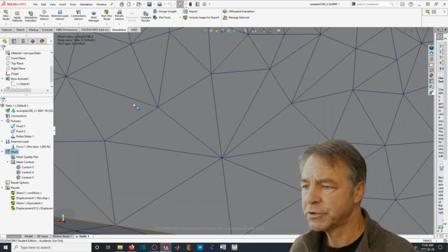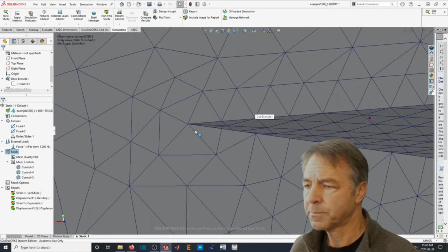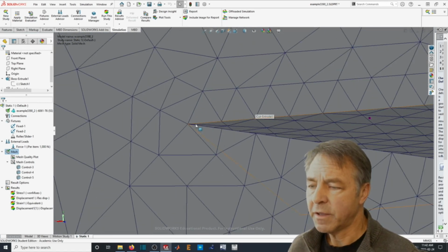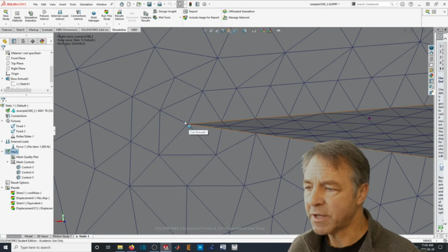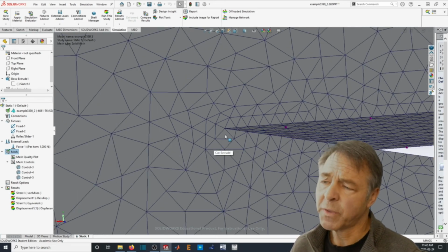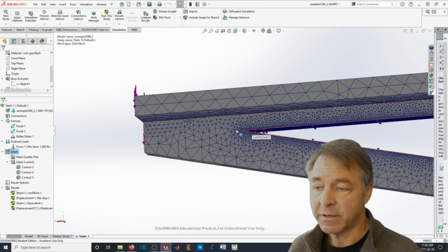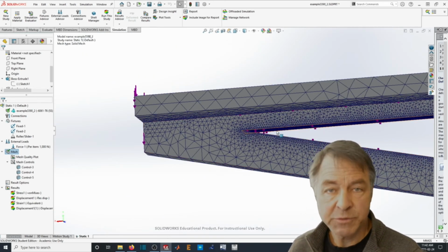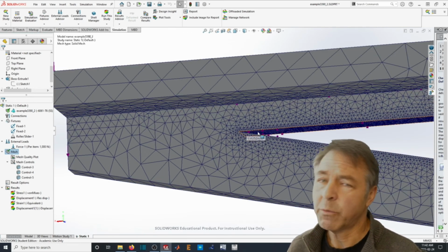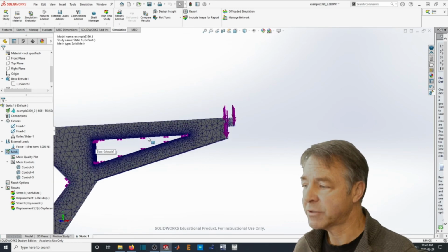So if I go to this and show the mesh, whoops, you can see that the corner, even though I had stresses that were very much smaller than here, I'm really basing that on elements that are much too big to really resolve that stress. So we know that there's going to be high stress there, and that might be a feature in our design that could stand to be edited, but we really can't trust the numerical result of how high that stress is.